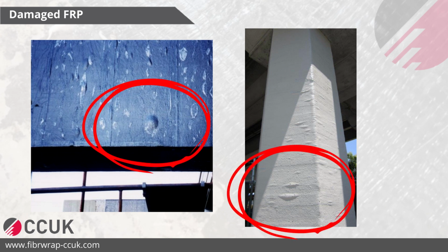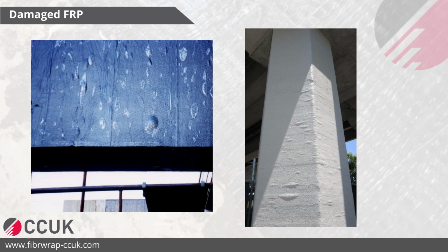If it has not been applied correctly, once it is cured, you can do a tap test, and then you can make sure that it is bonded correctly and there is no hollow sound or air bubbles or anything in there. Because if this application is not done correctly, we can get these kind of results where you